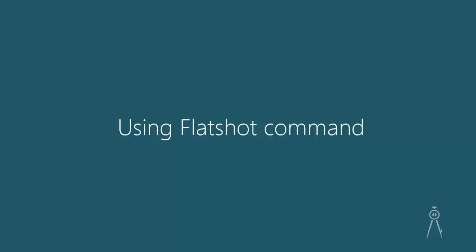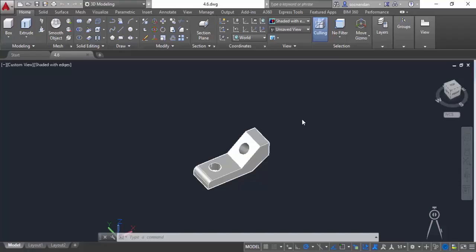In this lesson, I'll tell you about the flatshot command, which is a very efficient method of creating 2D geometries from a 3D model. So here we have this 3D model, and let's say that we want to create different kinds of 2D geometries like top view, front view, isometric view using this model. So you can directly create those kinds of geometries in the model view using flatshot.